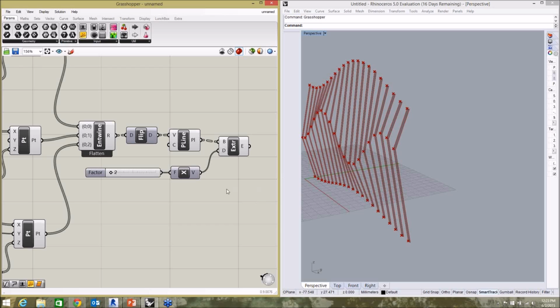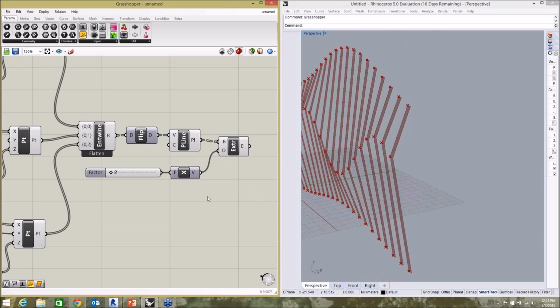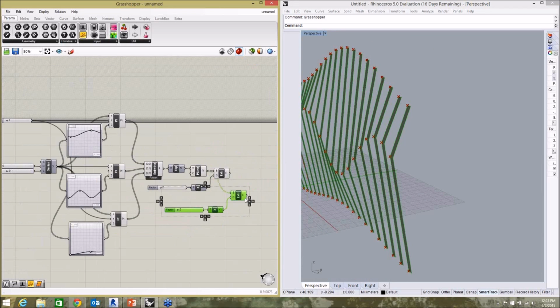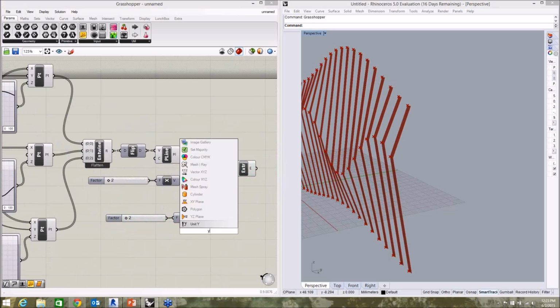And then I'm going to offset or create some geometry in the other direction as well, in the Y, because right now this is just a flat plane. There's probably some better methods you could use. You could probably create a closed box component that would snap to these, but for the purpose of showing you some really simple Grasshopper techniques, I'm going to show you that you can copy paste this again and do this now in the Y direction. So I'm going to pull this one over here, replace this X with a Y. Okay, I want to create an extrusion, and we're going to say Y.